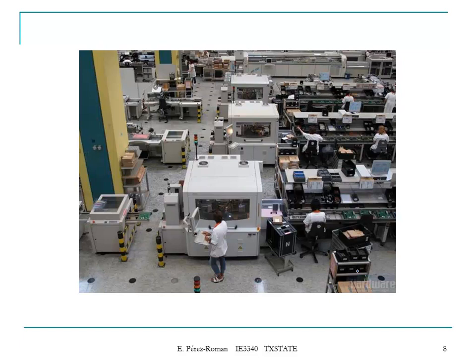You have a machine that is usually your bottleneck, basically. It's the one that dictates how many units you're going to be producing. Because if the machine is able to hold a unit every 5 minutes, you don't want to put a lot of units before the machine because that will create a queue.